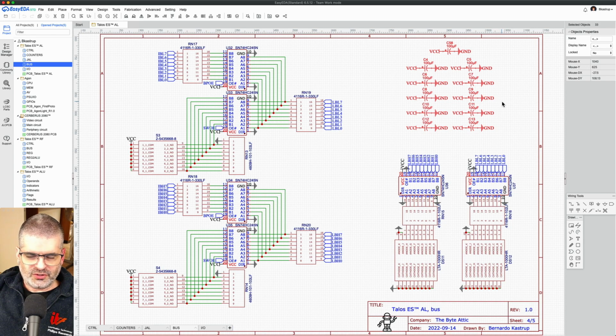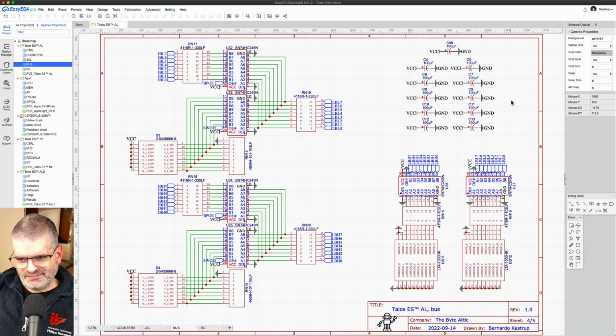There are more chips on this board, and I didn't really calculate anything. I'm just doing it by feeling, and I think I placed 10, and I thought, oh, I'd like another one over there. So yeah, this is over-engineered, but they cost nothing. And since I'm using a 4-layer board, of which 2 are planes, the power plane and the ground plane, then they don't even make the routing any more difficult, because wherever I put them, there will be the 2 planes